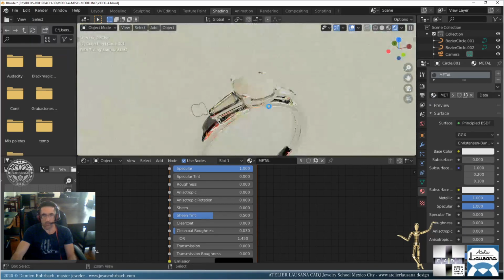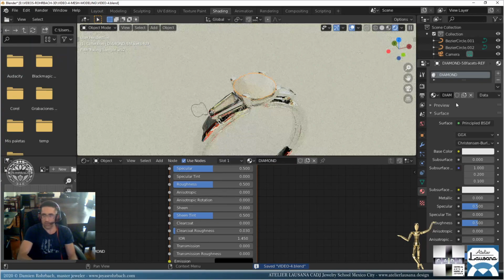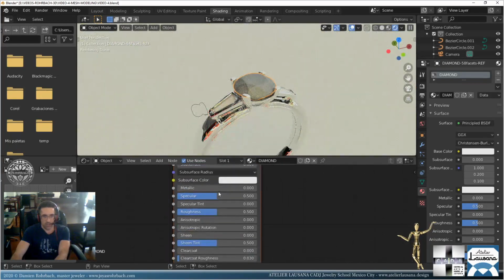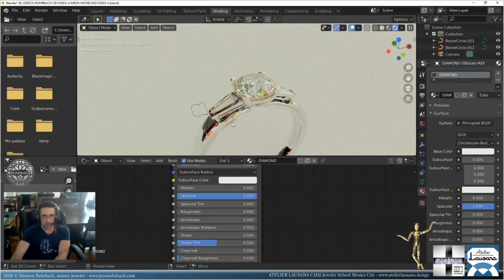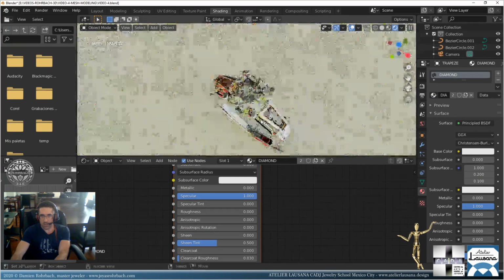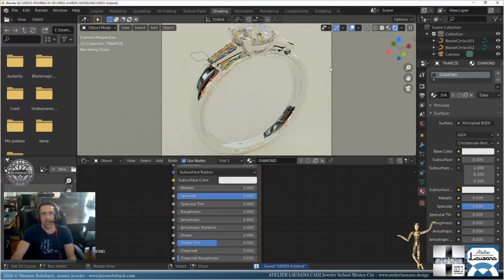All right. Now, this guy, new diamond. Let's go transmission 1, IOR 2.43, metallic 0, specular 1, roughness 0. Okay, we're looking good. This is diamond, and this is okay. The baguette, the trapeze baguettes.